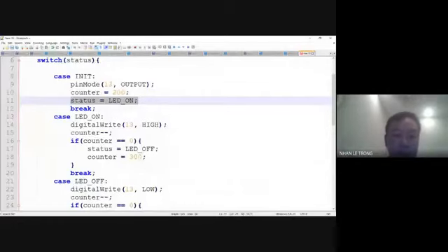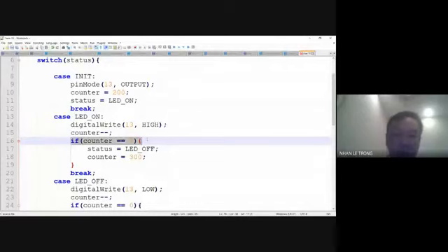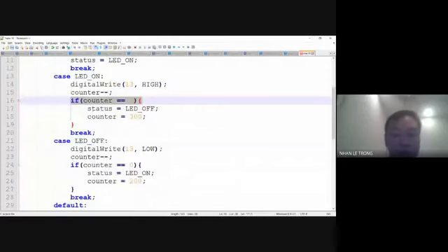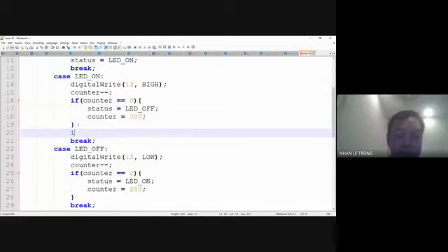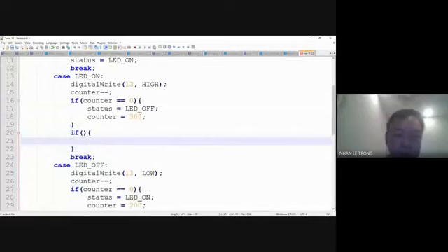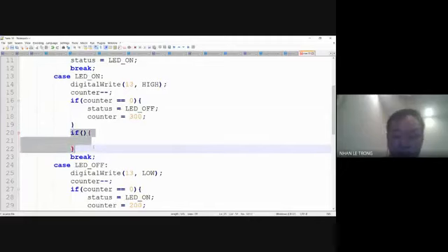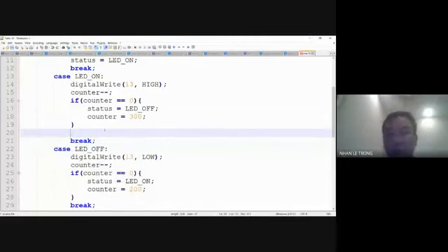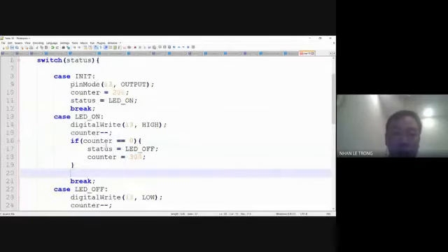And you can see with the state machine, you only need variables and if statements. You never need a loop, a for or a while. And in your source code, very rarely do you use a nested if. Normally the if is just like this, and if you have another condition, you will have another if, and something to change the status. You don't need the nested if. When you don't have the nested if, your program is very easy to follow and very easy to understand.